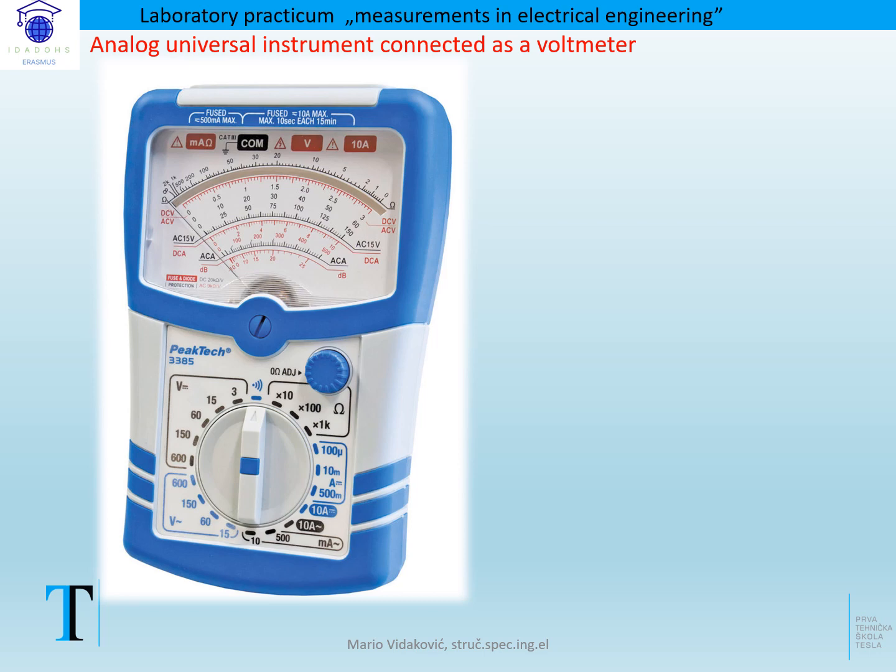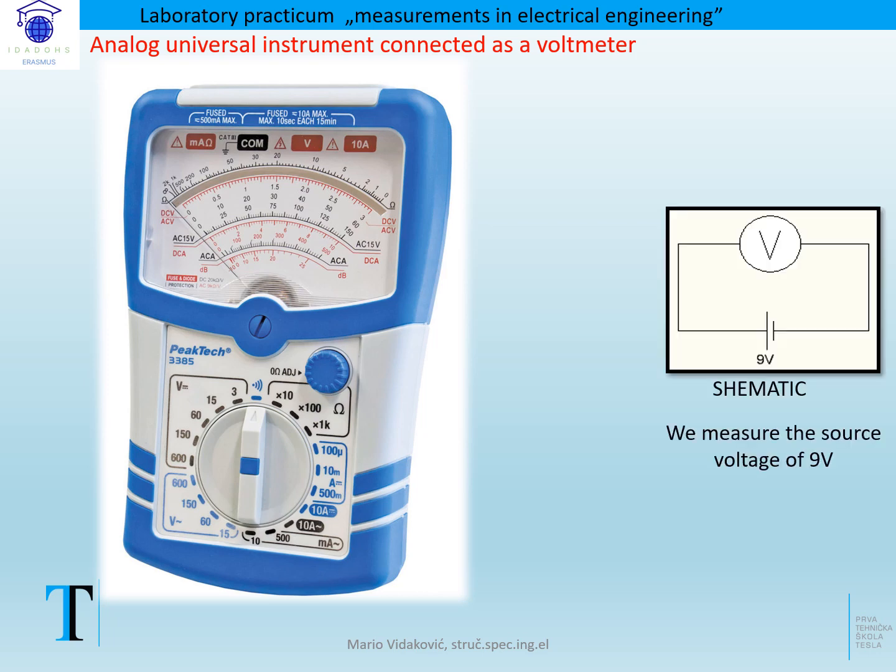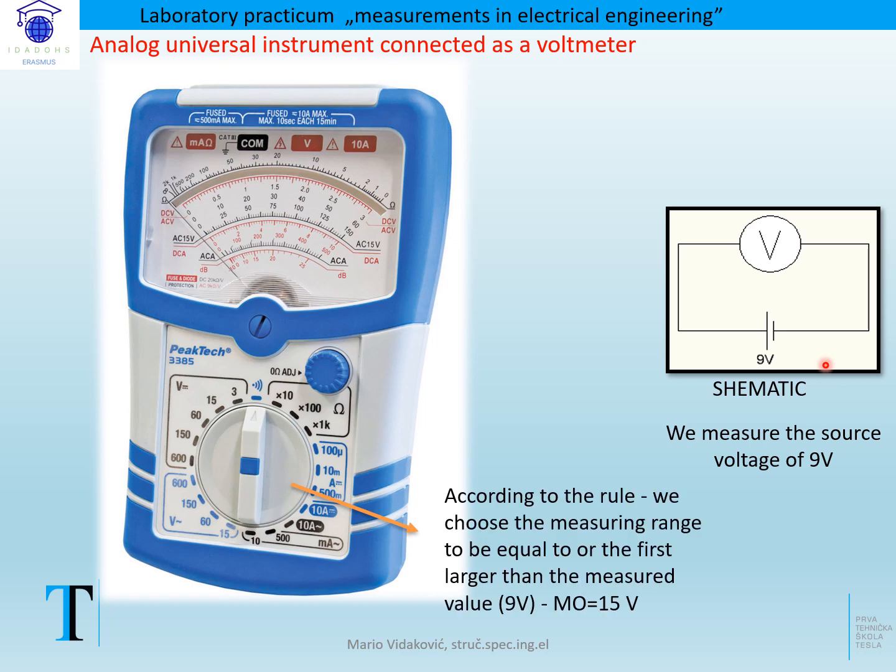Now we are going to see how the analog universal instrument is connected as a voltmeter, because in our practice we are going to use it like a voltmeter. This is a schematic. It's very simple. We measure a voltage of 9 volts. This is the voltmeter, and this is the 9 volt source, plus to plus, minus to minus. According to the rule, we choose the measuring range to be equal to or the first larger than the measured value. The source is 9 volts, so we must choose the measuring range, or measuring scope, of 15 volts.